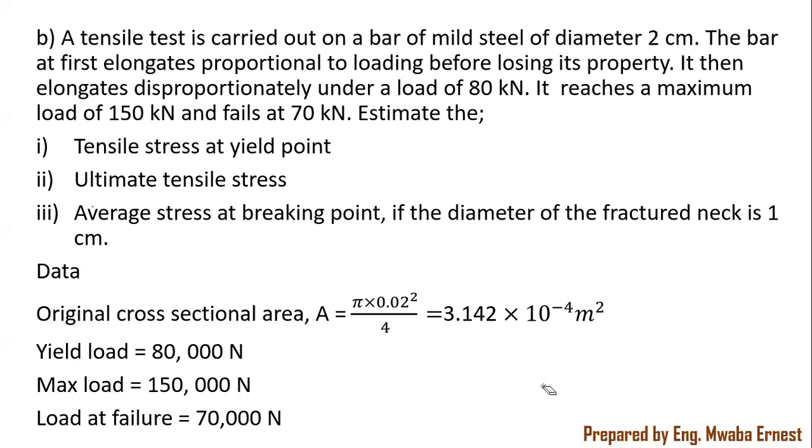So the first one we're starting with is the tensile stress at yield point. What is the tensile stress when this material is yielding? So go ahead and pick up the formula for that. The formula for the yield stress is simply the force at yield point, or the yield load, divided by the original cross-sectional area. So here we've just said yield load over area.